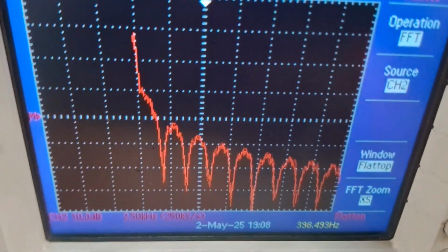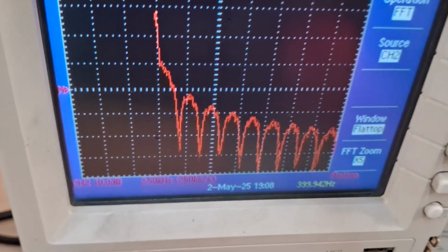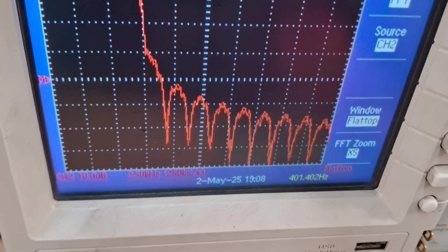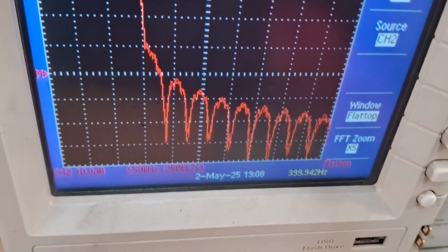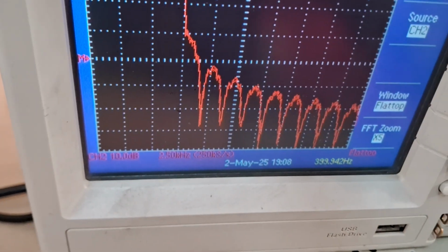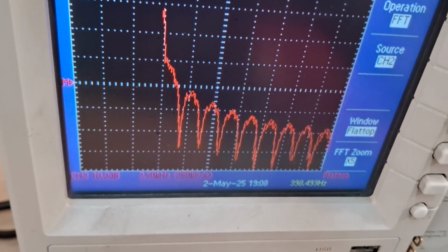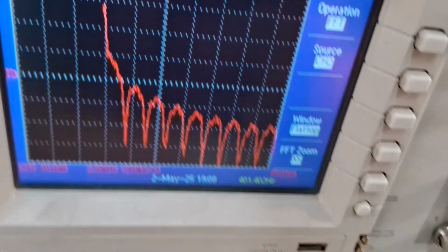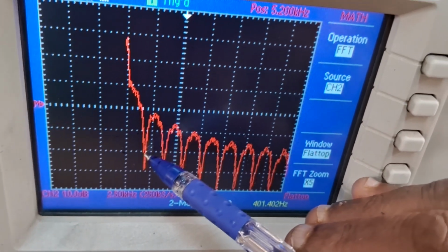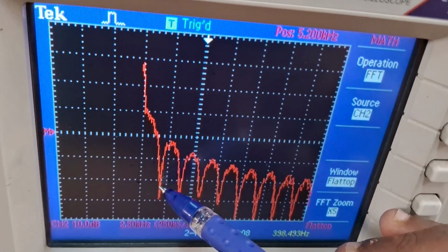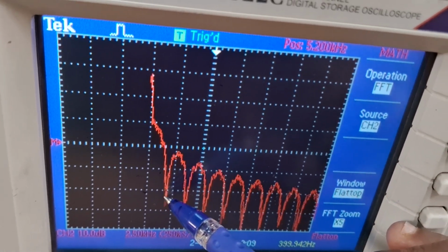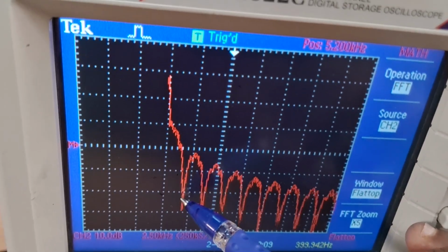Now how do I measure the zero crossing of this? If I want to observe the FFT of a rectangular waveform, rect(t/tau), it is nothing but a sinc function, correct? So the function is nothing but sinc, and the first zero crossing frequency will correspond to 1 upon tau, that is the duration of my pulse. What is the duration of my pulse?